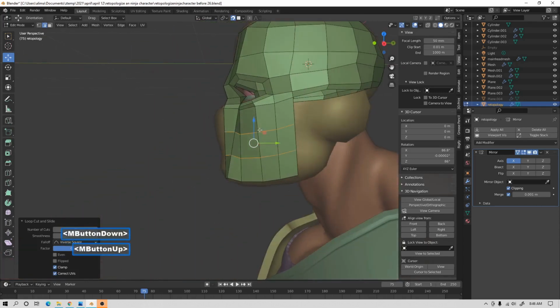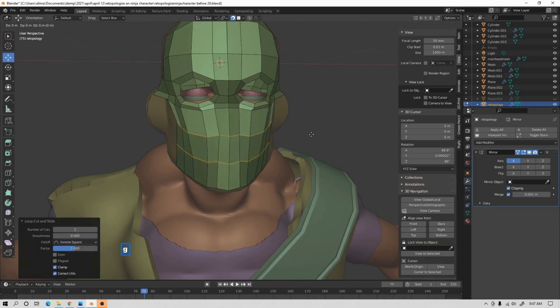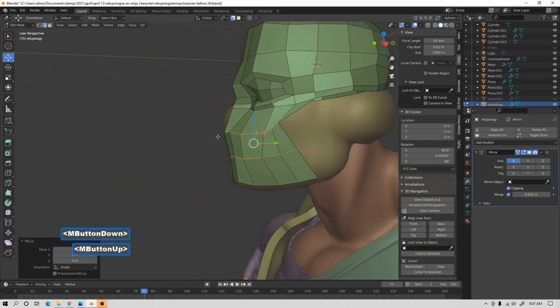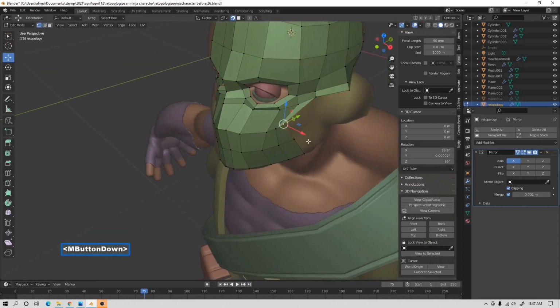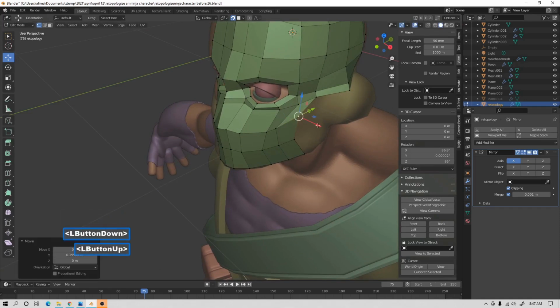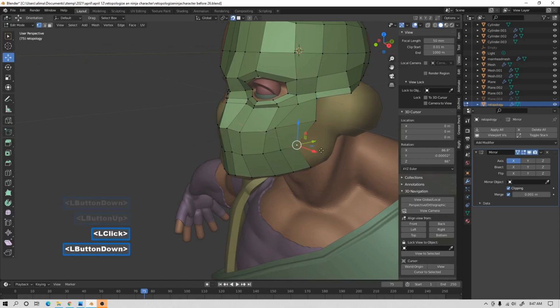When I hold to the side, you see how the edges aren't snapped to the face, even though we have snapping on. So when you put in new edge loops, you press G, we'll left click, and now you can see that they're snapped. And this right here came forward, so we'll drag that back.